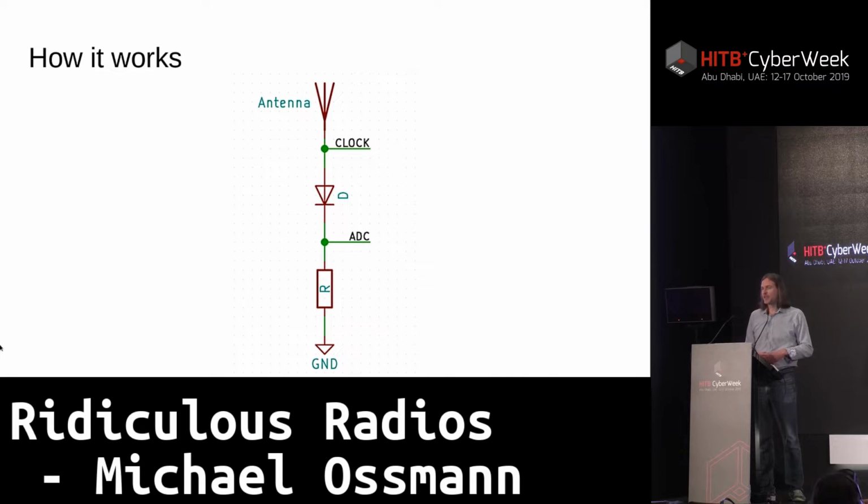That means the signal that came in on the antenna was reduced to baseband, to the vicinity near 0 hertz, because that was the difference of those two frequencies: the frequency over the air coming in on the antenna and the frequency of the clock, which a radio designer would call a local oscillator. But in my case, I was simply using a feature of the microcontroller that is a clock generator.